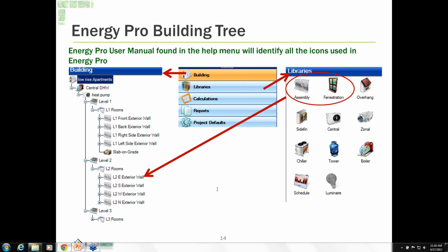So would you perform exhaust fan calculations on a low-rise rehab when sampling is involved? Yes, I would. I like to. I'm a real detailed person, so I like to get as much information about a building as possible. And if I can get information on the exhaust fans, I will include that. And there's ways of showing with the two-model approach how to get savings from the fans. So you will get a baseline fan when you model it, and you can do another model, a two-model approach, and compare it and see what my fan energy use is for the improved building.